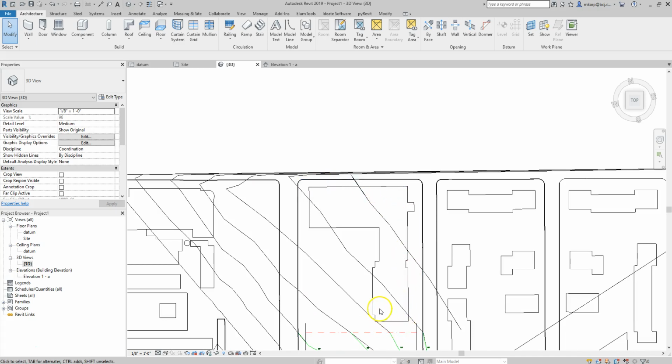If you have a Rhino file of the site, or you've already started making 3D buildings, that's okay. We can import the Rhino file in and then turn it into Revit objects. And I've attached a link to another video on how to bring Rhino objects into Revit. Basically, all you can do once you bring them in is trace them. And you're going to want to do that because you do not want to leave it as a Rhino object. You can trace it very quickly into Revit components and make it work in your model.